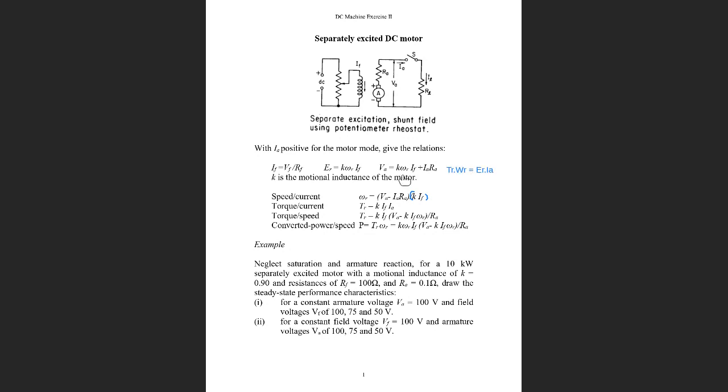Okay, so in addition to these three equations, we write down one more equation here, although we mentioned this one in lectures. On the armature, we have the induced voltage E_a and the armature current I_a. The product of E_a and I_a represents the electrical energy here, and it is this electrical energy that is converted into mechanical energy in terms of the torque and the rotation speed.